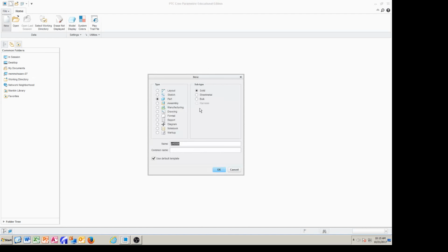Okay, I'm going to start and type U support. That's a file name. Please do not add anything else. Just type the name of the part, because we're going to create a bill of materials that will automatically transfer all this information to that bill of materials, so we don't want any other miscellaneous information.